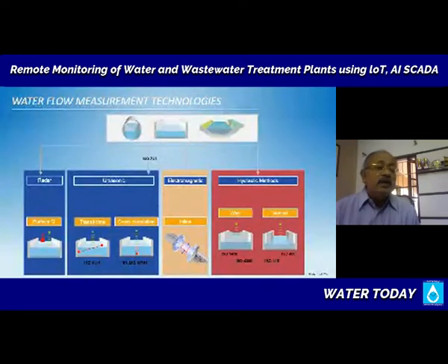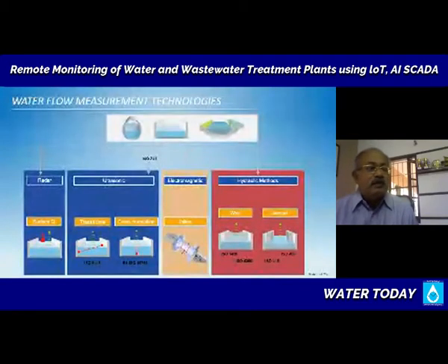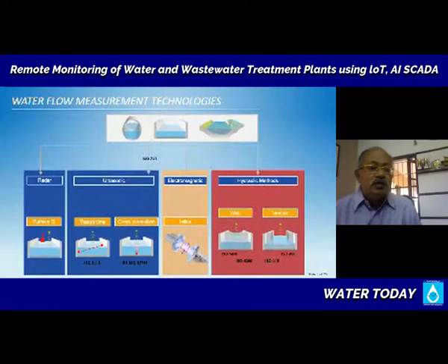Then, of course, there is the highest frequency, gigahertz range radar measurement, which, in water that's flowing, you can use to measure the surface velocity. This radar is something that policemen use in speed guns to catch overspeeding vehicles and things like that. So the same can be used to measure surface velocity. So you can measure water flow very accurately in irrigation canals and things like that, wastewater flow in a sewer system, etc. These are all possible with radar technology.